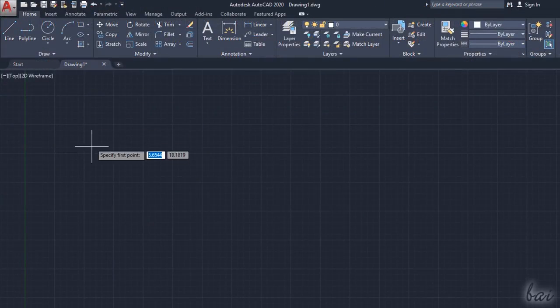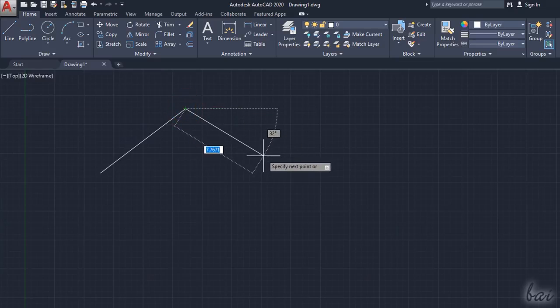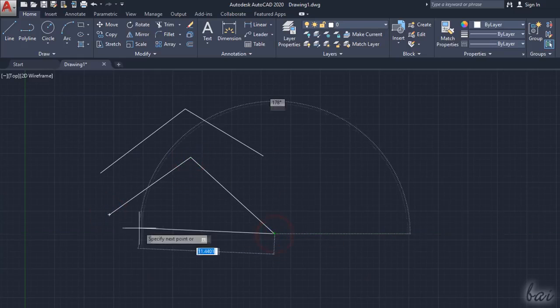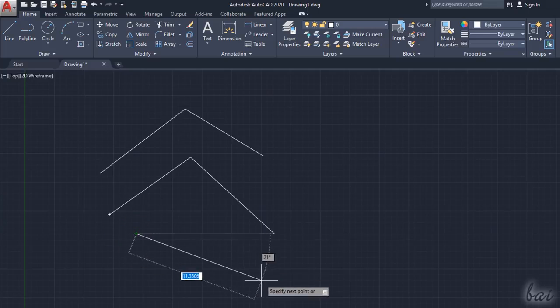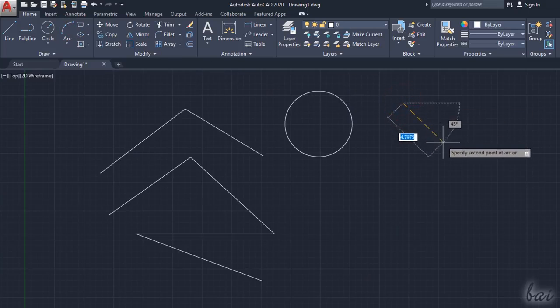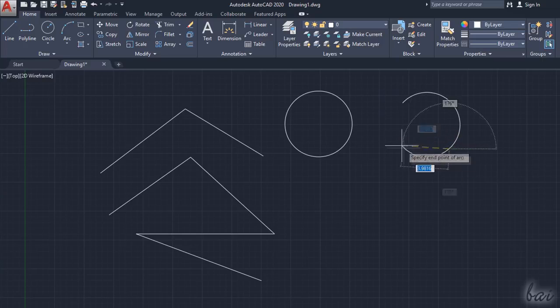Use Line or Polyline to draw segments inside the project. Fix the first node as starting point and a second one to place the first segment. Then you can drop consecutive segments sharing the last node until you use the Escape key to stop drawing. Use Circle to drop circles by fixing its center first and then a second point for its radius. Enable Arc to draw an arc by fixing 2 points to define the basic segment and then a third one to fix the arc curvature.